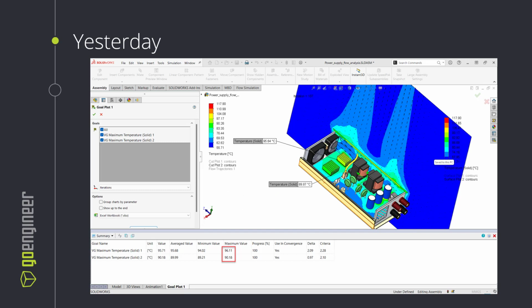So as shown on this slide here, we tried maximizing the performance of our components by introducing a second fan. And to help along the accuracy of the project, we also extended the computational domain of the surrounding fluid medium. This did help a bit, lowering our temperatures slightly, but we saw that this type of change was definitely in the right direction, and so we'll focus on the accuracy of our setup and continue to adjust our study by replacing a few of our existing features with new ones. This process will give us better accuracy of our heat transfer model and a more definitive verdict of our performance of our two integrated circuits. So let's go on back to our SOLIDWORKS screen and let's set up our project with these new conditions.